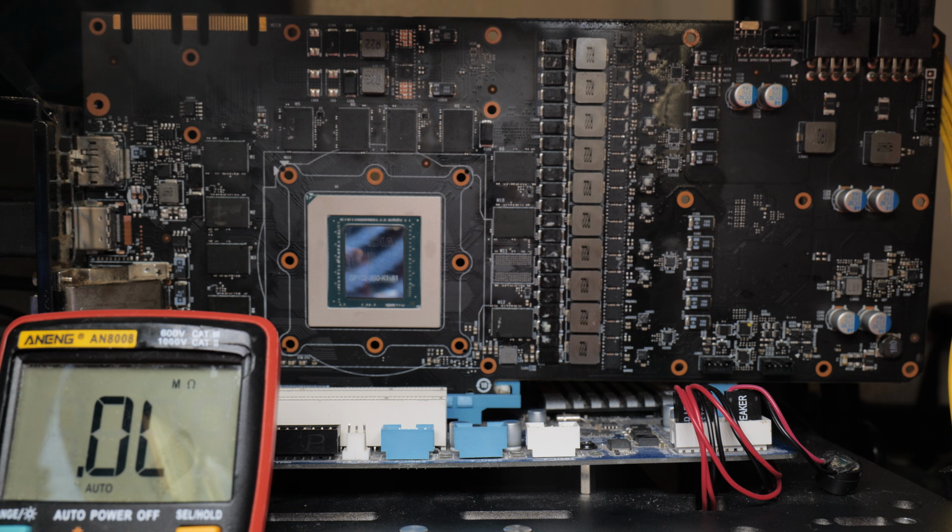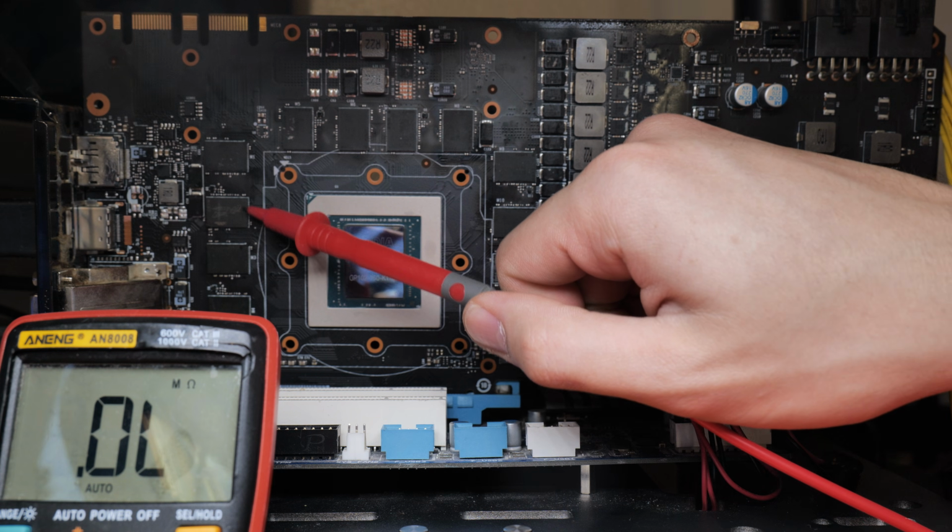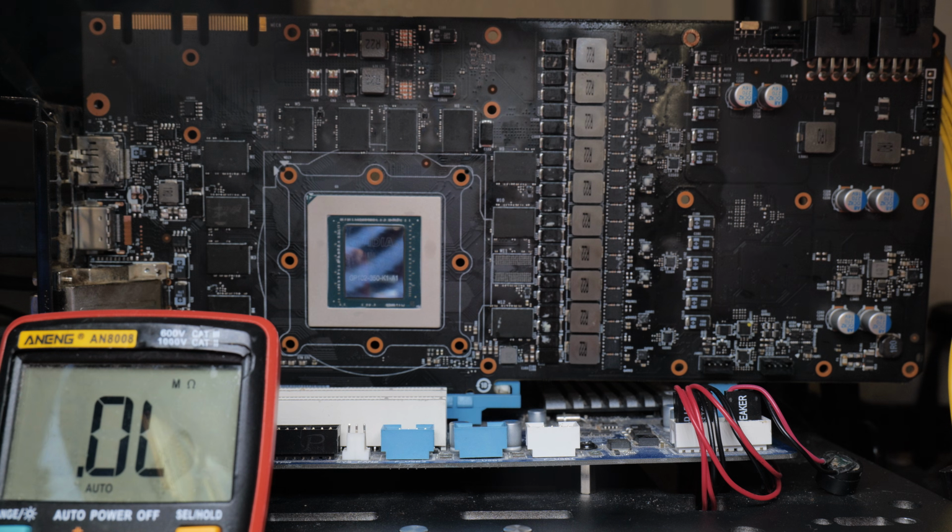Okay, so as you hopefully saw, or at least part of, I replaced the memory bank at E0. You can tell by the tone that it's a bit different from the other ones. Anyways, before we turn on the card, we want to check for short on 2 power rails.